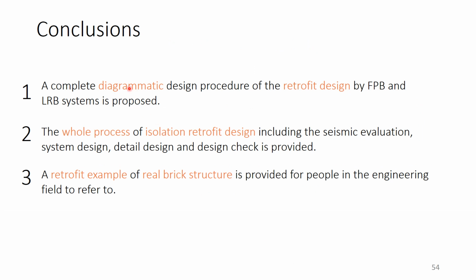So here are the conclusions. First, in our thesis, a complete diagrammatic design procedure of the retrofit design by FPB and LRB systems is proposed. Second, the whole process of isolation retrofit design, including the seismic evaluation, system design, detailed design, and design check, is provided. The third is a retrofit example of a real brick structure, Datun Elementary School, provided for people in the engineering field to refer to.